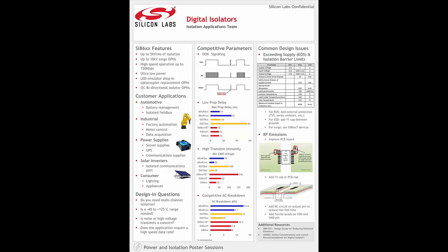If they're able to adjust their design to meet these specs, that's great. If they can't find some over voltage or over current event that might be causing the issue, they can add protection to the device, such as a TVS diode on the supply, low series resistors on all of the pins, and that'll just help those resistors act as cheap fuses to protect the part.